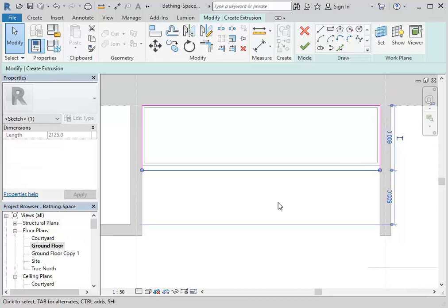the door thickness is going to be 20 mil. So this is the baseboard of the cupboard. The doors will sit flush up against that, so they'll be 20 mil less than 600. Okay, so 580.